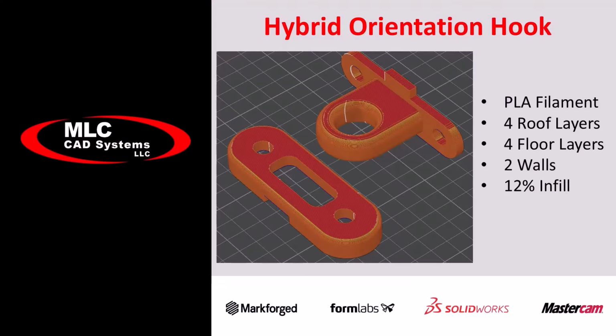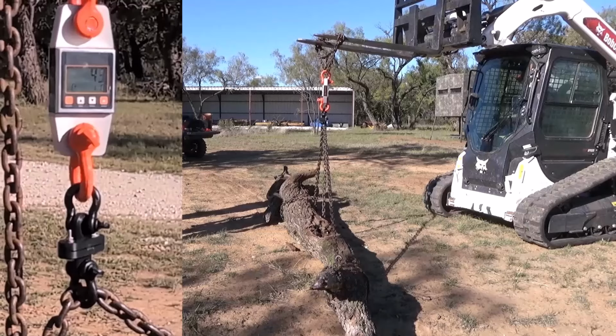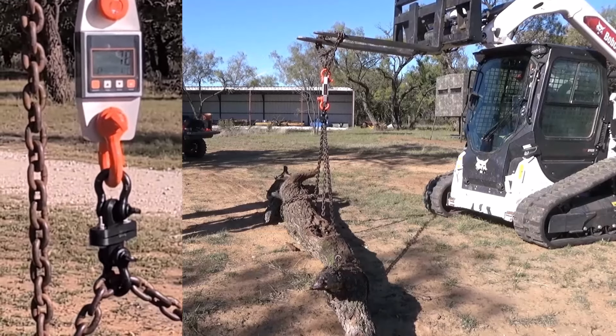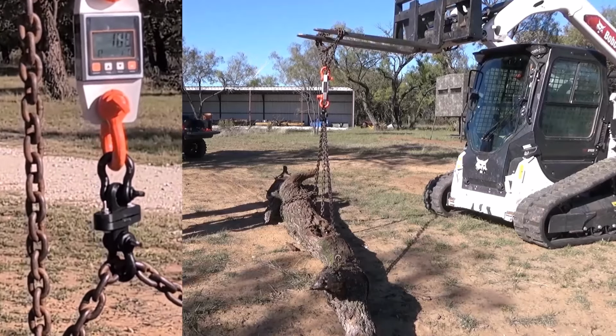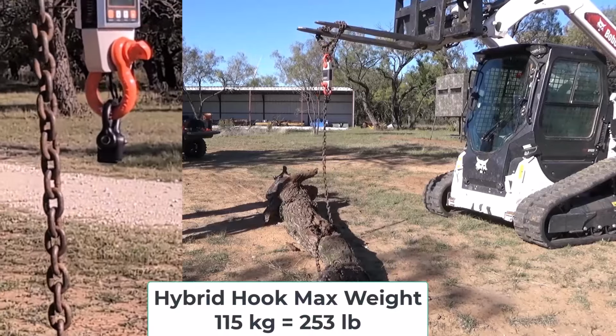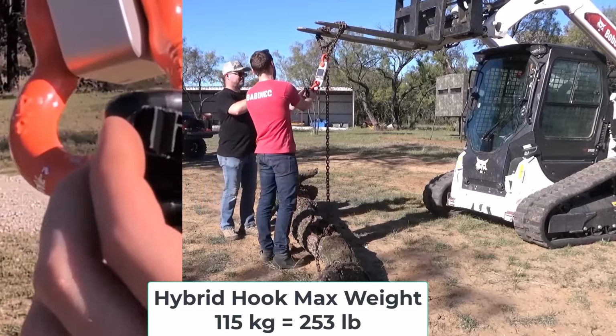Test number 3 is now our hybrid hook, which takes advantage of the strengths of each of the print orientations from our previous experiments, and the rest of the parameters are all the same. 30, 40, 50, 60, 70, 100, 110, 115. All right, that actually made it a lot further. And the hook survived. It actually broke along the flange.